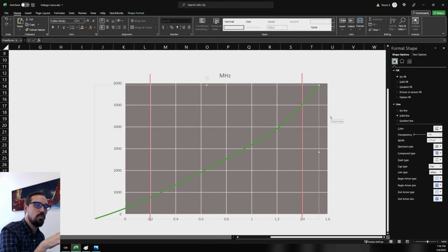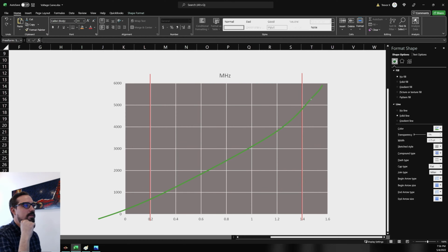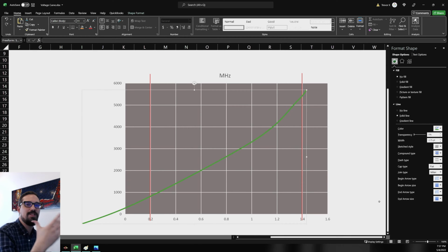And this does work in theory. At -28 offset, my 5950X hits 5 gigahertz consistently. So when we're talking about your average boost speeds, it will hit an average boost speed of 5 gigahertz, no problem. Now the problem is this. We may be moving this along the curve, but look what happens at 0.06 volts. Now if you see I move the curve to the left at 0.06 volts, we're actually now running at 2 gigahertz.